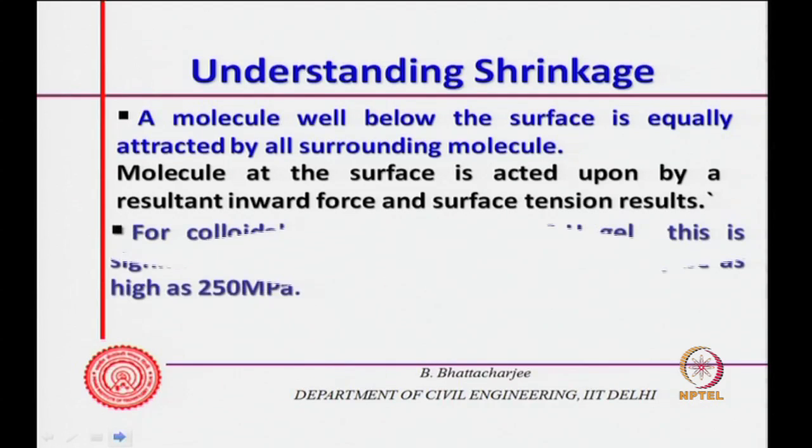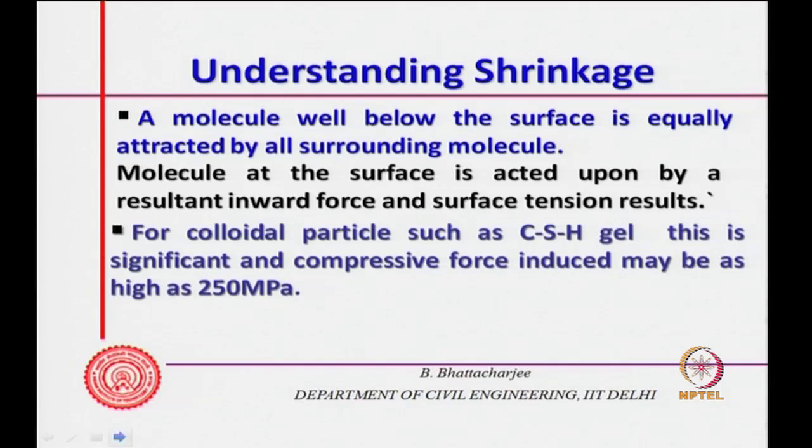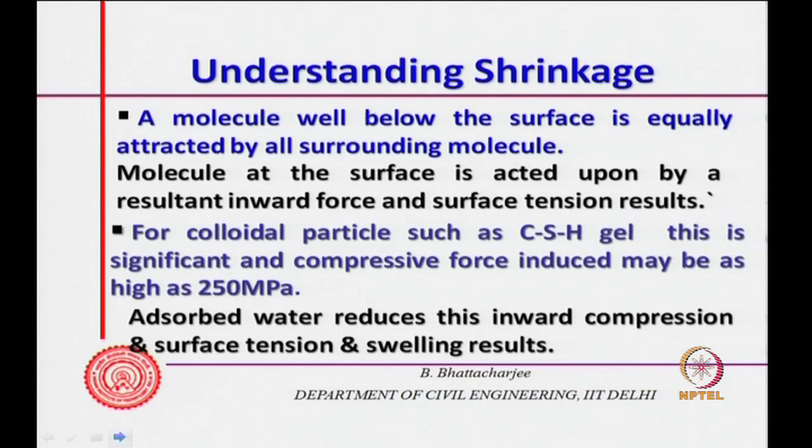For colloidal particles such as C-S-H gel, this is significant, and the compressive force induced could be as high as 250 MPa. So, if it is dry, there is a compressive force acting downward into the skeleton, and this could be as high as 250 MPa. Now, I bring in adsorbed water, which reduces this inward compression and surface tension, and swelling results. So, it reduces the inward compression. In other words, the surface tension of the C-S-H system has reduced. So, swelling will result.